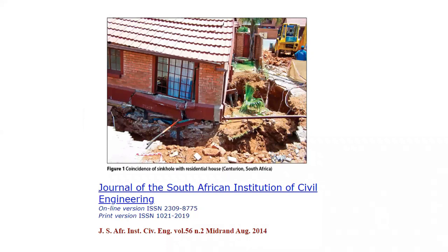Drainage in Dolomite areas, and water leaks in areas where there's dolomite, is quite a scary thing. If you've ever seen any of the sinkholes around Carltonville, some in Midrand, and a lot in Pretoria, you'll know that the ingress of water into any dolomite area is a real problem.